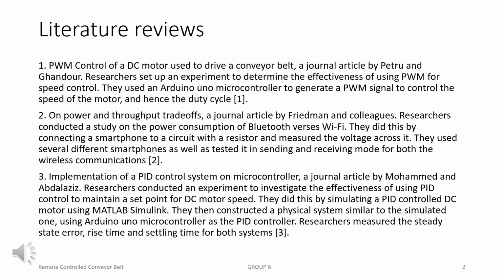They then constructed a physical system similar to that simulated one, using Arduino Uno microcontroller as the PID controller. Researchers measured the steady-state error, rise time, and settling time for both systems. They concluded that both systems were effective and managed to meet the requirements of having a steady-state error of less than 5%, rise time less than 2 seconds, and settling time less than 4 seconds.